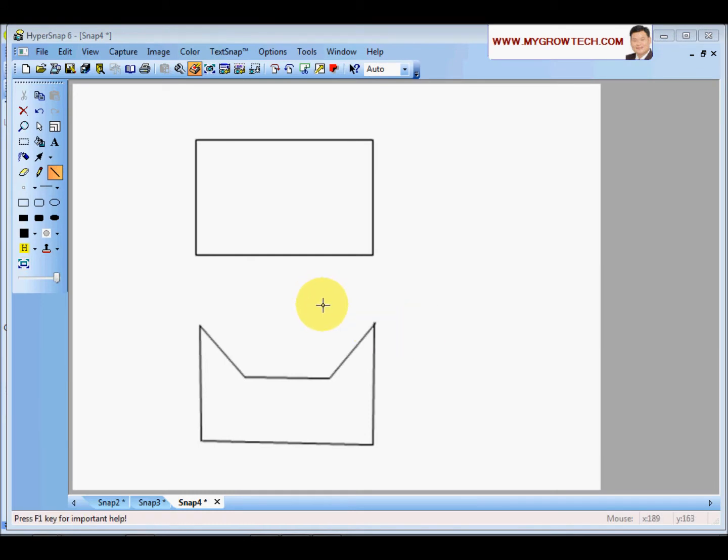What is on, in, out, and touch point? On means the cutter reference from the top is always at the center. In means this cutter reference is always tangent inside the contour. Out is always tangent outside the contour. Okay, from the top.